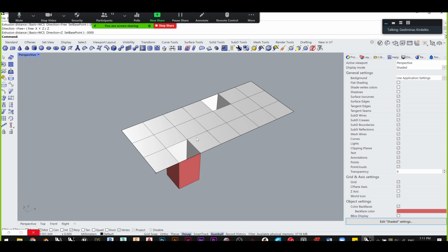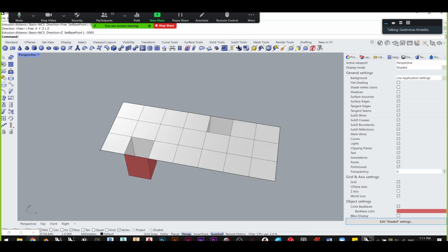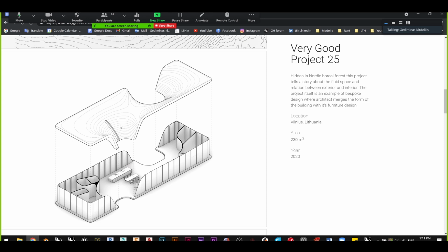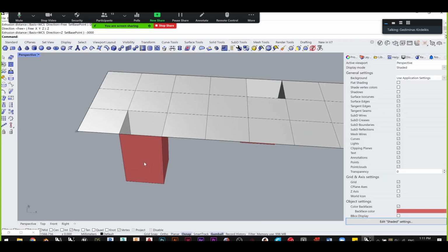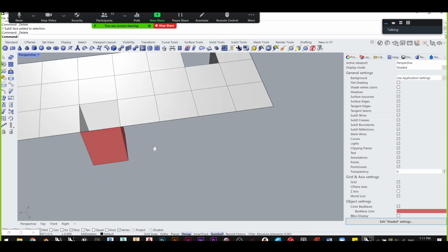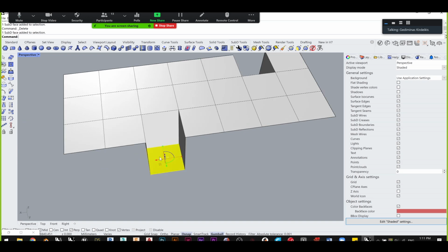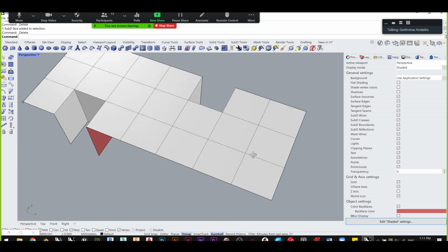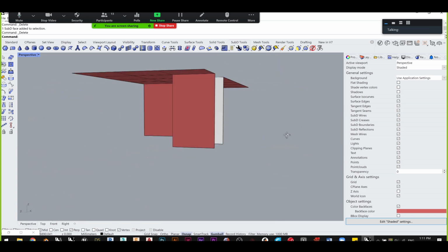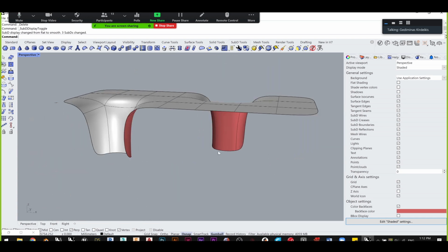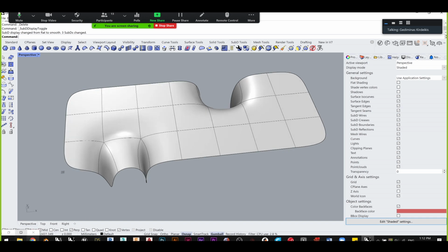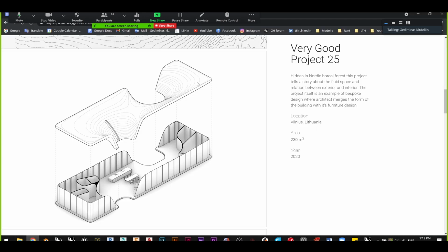And topologically speaking, it's not the same as what I want here, right? Because there shouldn't be any surface here and there shouldn't be any surface at the bottom. So I will simply just delete them. Delete that surface and the bottom one. Easy. Same thing on this side. That surface and the bottom one both get deleted. So now, topologically speaking, these two are exactly the same as this geometry right here.